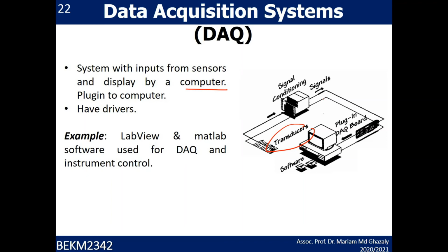First you need to consider what the next step after the sensor is. The sensor reading is in analog, so you need to look at the signal. Is the signal a very small value? If it is small, in millivolts, you need to amplify it, or if there is too much noise, you need to use a filter. This is where the signal needs to go through signal conditioning.